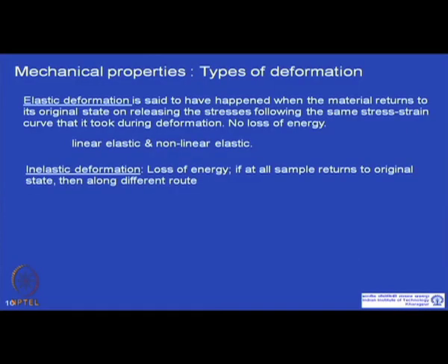Second is inelastic deformation. In elastic behavior, if you give the stress, give the force, the energy is stored in the material. So, when you release the stress, that energy is given back. So, you get back to the original state. Whereas, in case of inelastic deformation, when you apply some force, the energy is lost.